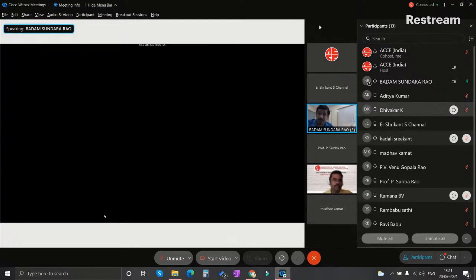In the case of embankment, after post construction, you require some sort of CD testing also. Generally, we design for the embankments. That embankment requires the C and phi. That depends upon the time of loading and the nature of loading.